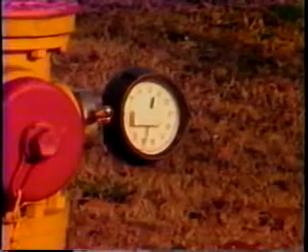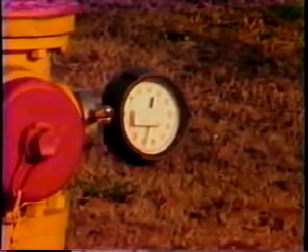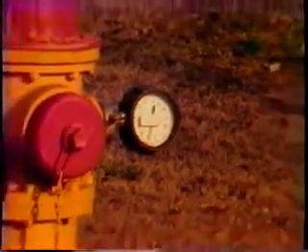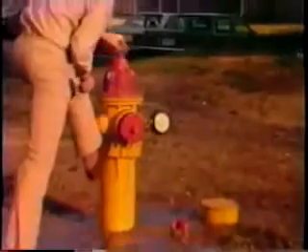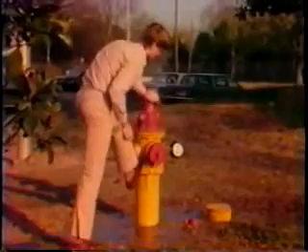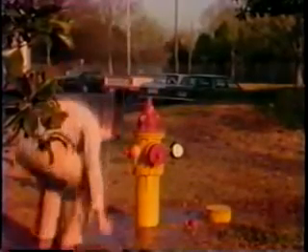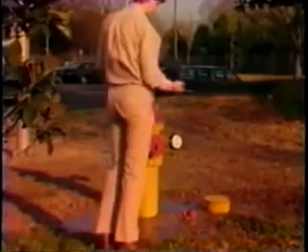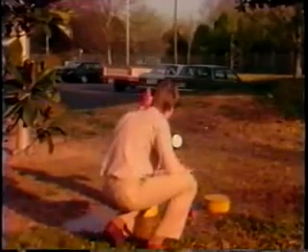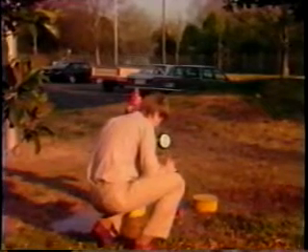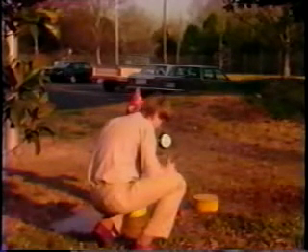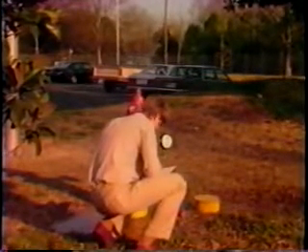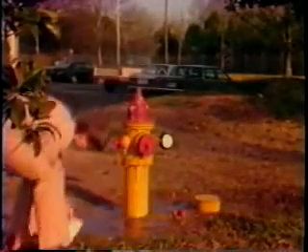Next, you actually attach the gauge to the hydrant, making sure that you've got it good and tight. Next, open up the hydrant. This time the pressure gauge should indicate the static pressure. Take a reading of the static pressure once you have the hydrant completely open. The pressure gauge should not be bouncing around too much. If it is, try to find out what's happening. Are pumps kicking on and off nearby, or is a pressure reducing valve opening and shutting? Usually though, the gauge should remain fairly stable within 1 or 2 psi.